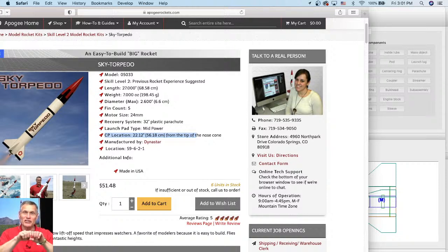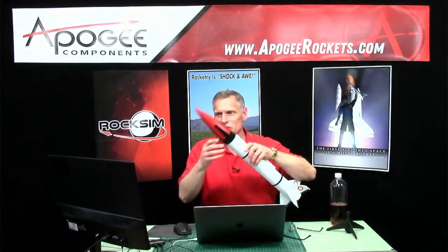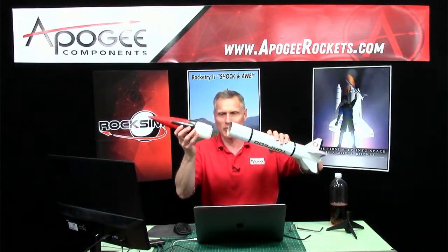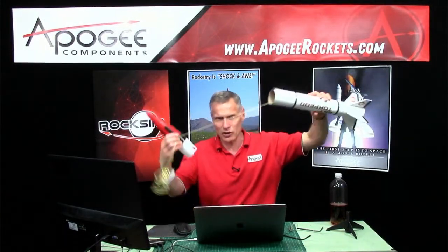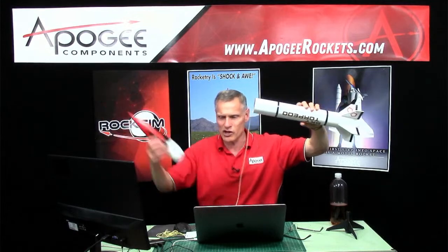So the advantage of elastic is you have less chance of zippering the rocket. Okay, so let me show a zipper. Here is a rocket, and if you have a Kevlar cord on it, the Kevlar cord will stretch out, elongate to the full length.